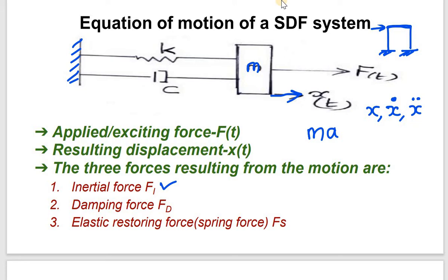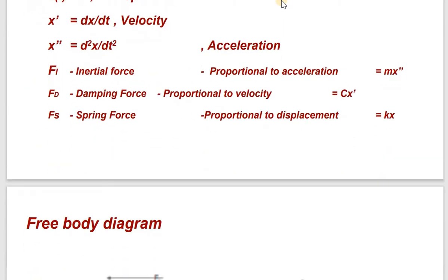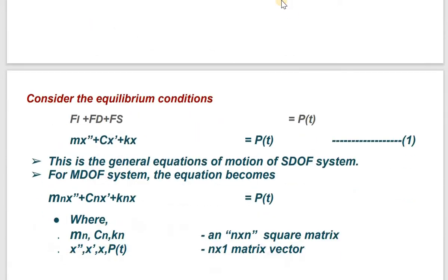So you can see here the force is acting in this direction. Then stiffness acts in the opposite direction, as shown here. The stiffness force is K into X. Then damping is C into velocity; damping is with respect to velocity. So these are the different forces that are acting. With these forces only, we will write the equation. So the equation is like this.